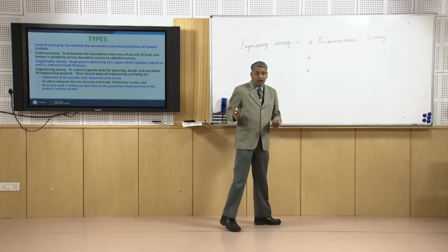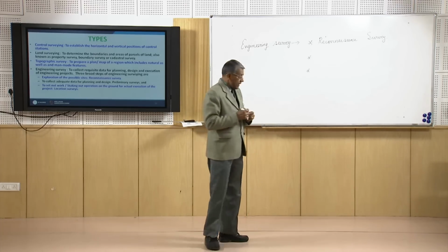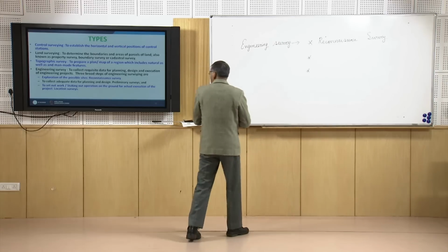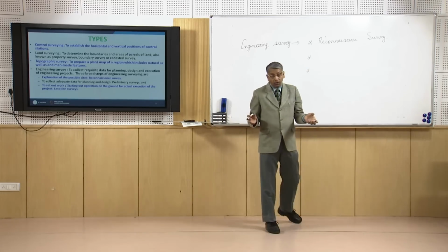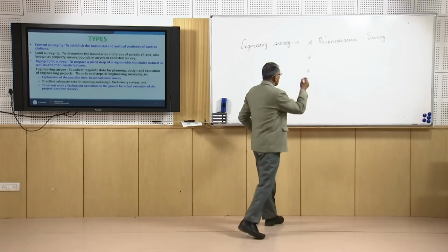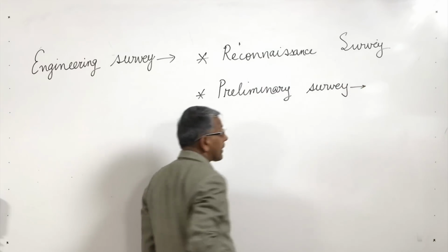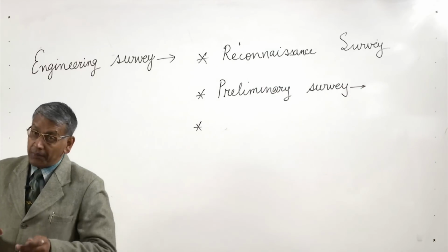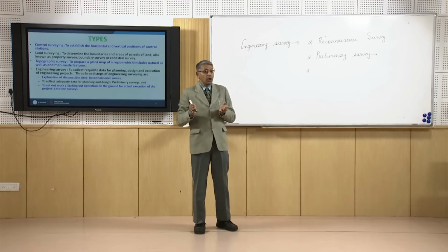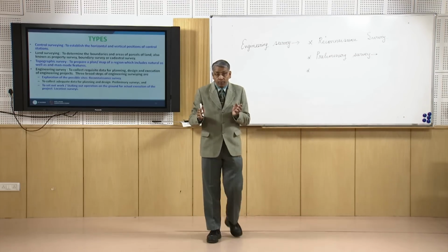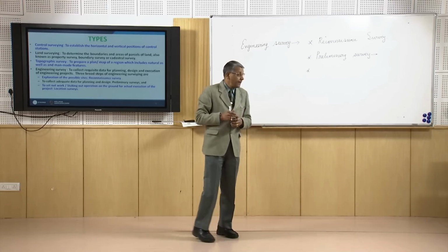Then after reconnaissance survey we collect the preliminary data, and then we plan our work. Then we go for preliminary survey. During preliminary survey we actually collect the different measurements or data about the surface which is of interest for the project.